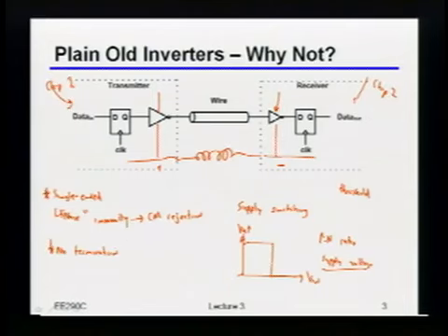But there's going to be one more really important one that just about everybody complains about. If the wire has sufficient loss, both transmitted 1 and 0 will be below the threshold. Okay, that's actually an interesting one. It depends on what the data pattern was. If the data pattern was sort of balanced, then maybe I could magically balance it around the threshold on the other side. But you're right that if I had a long string of zeros and I had some low-pass filtering, I may not make it back over.